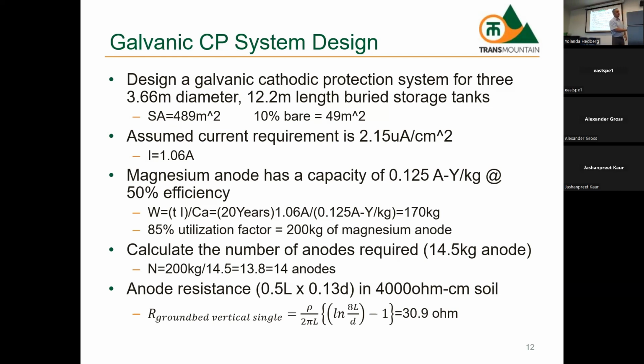I think in this case, the steels were actually coated. I think I have 0.9. Yeah, 10% bare. So that essentially tells me that it is coated. You don't have the entire surface area exposed to the electrolyte. You only have 10%.